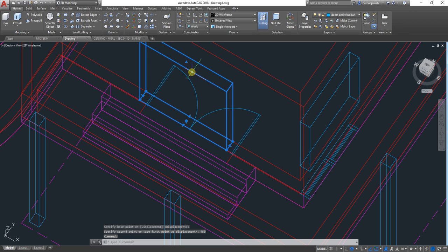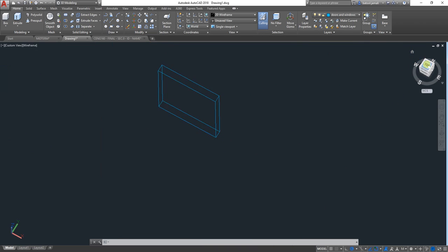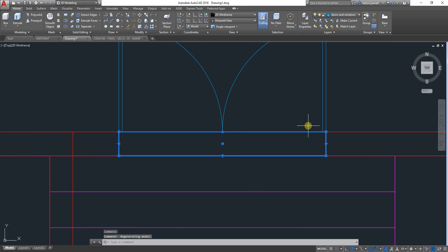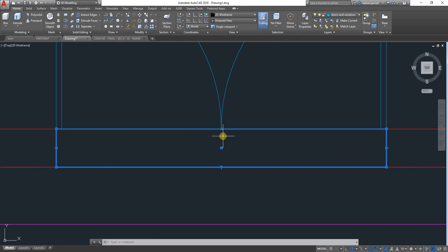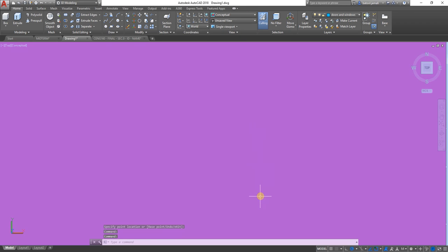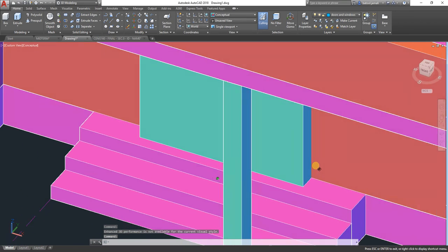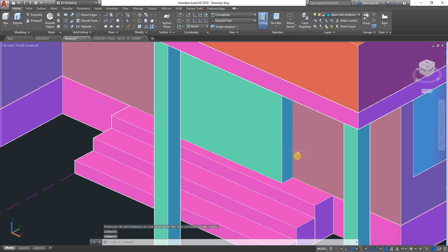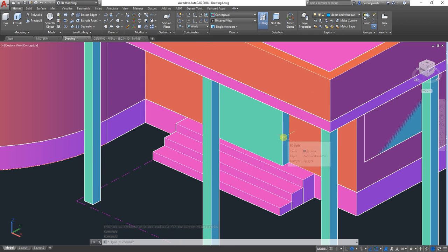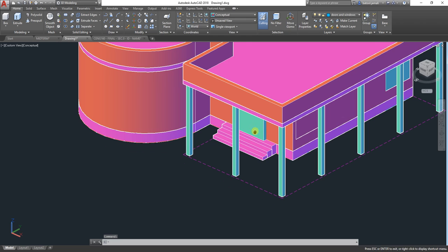Sometimes when you have the box like this and you make the subtract, it will not be subtracted. You will have an error. In this case, you can just go back to the top of view, draw the box again and keep it in the correct position, and come here to this small arrow, click on it and move it a little bit up. The same for the other side. Click on the arrow and move it a little bit to this side. This will make your box have extra distance from outside and from inside. So when you subtract it, you can be sure that it will be subtracted. It will not be error, or you will not have any mistakes. So now we have all of them.